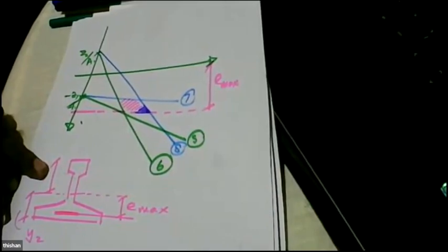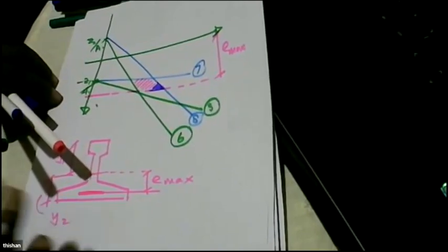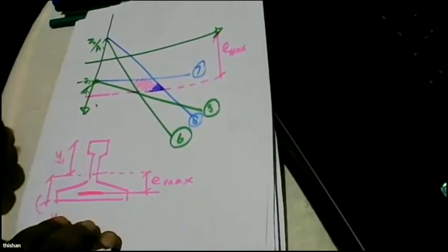So basically, what you see is we are designing using the same sign notation. The only difference between the simply supported case without concrete and the one with concrete is that when we use the one with concrete, we get composite action, and composite action will make the section more efficient because it's now bigger.